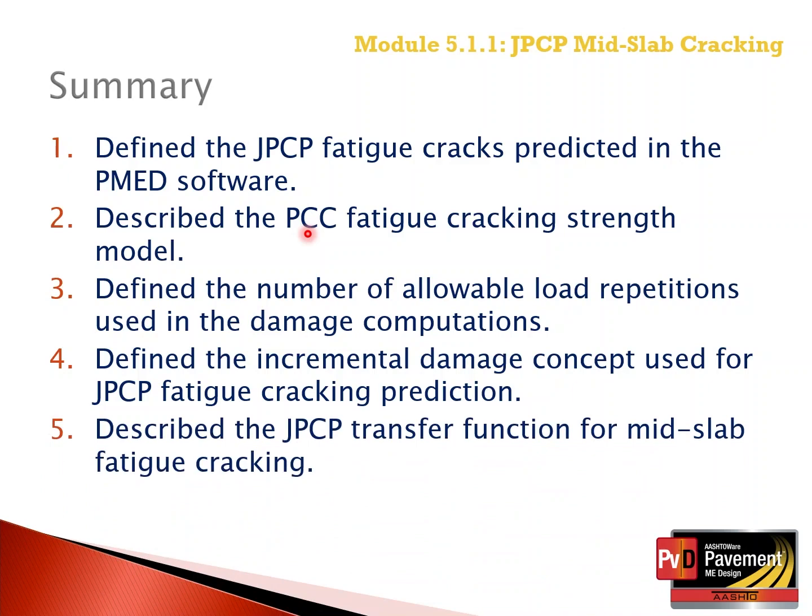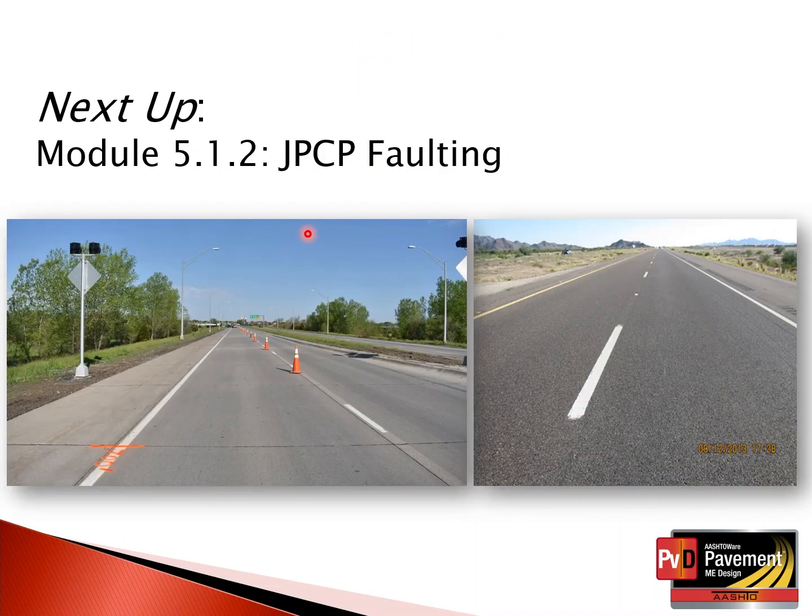And we describe the transfer function for mid-slab fatigue cracks. In other words, describing the transfer function relating fatigue damage, total fatigue damage, to percent cracked slabs. This ends Module 5.1.1 on JPCP mid-slab cracking. The next submodule of the training course sequencing is Module 5.1.2 on JPCP faulting for rigid pavement design.